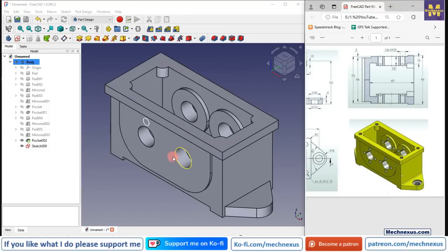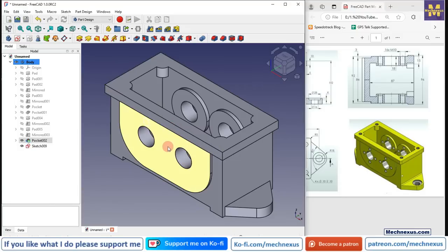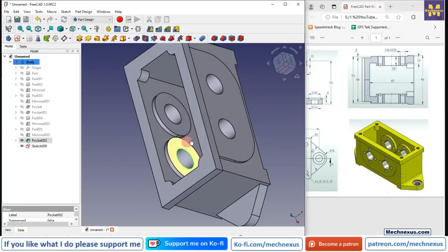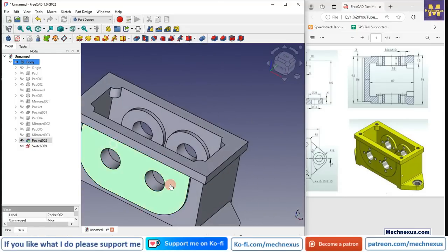You can see that here this is of the 18 mm wall thickness. So if I select this face and this face, so this is the 18 mm and here is the 18. So here is M10 at 16 mm. So tapping is up to the depth of 16 mm.